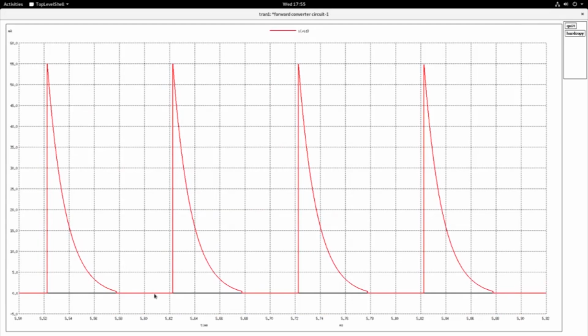You will see that during this portion the switch is on, and when the switch goes off, the current in the freewheeling circuit starts flowing. It exponentially decays towards 0. This is the shape of the core reset current flowing in the freewheeling circuit. I will revisit this later when I talk about the lossless flux reset and compare the two results.